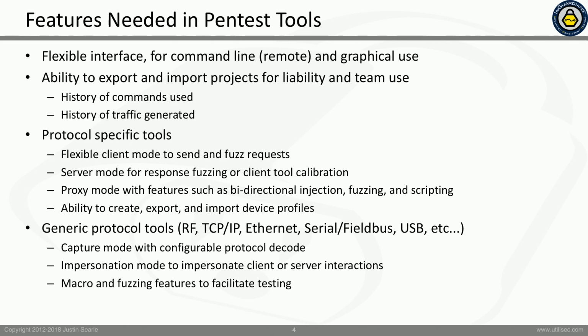Raw generic testing tools for things like Ethernet communications, okay? Raw Ethernet communications outside of TCP/IP. We have some in the IT world. You get into serial, fieldbus protocols. Virtually none. The closest we usually have for serial testing in the IT world are tools like PuTTY, or some type of minicom, something that gives me a serial interface that's ASCII only. Well, the problem is most of our serial protocols are not ASCII protocols. They're binary protocols, which means we need a binary tool to do that. Then we get into USB, and RF becomes all other interfaces that we may need capabilities for.